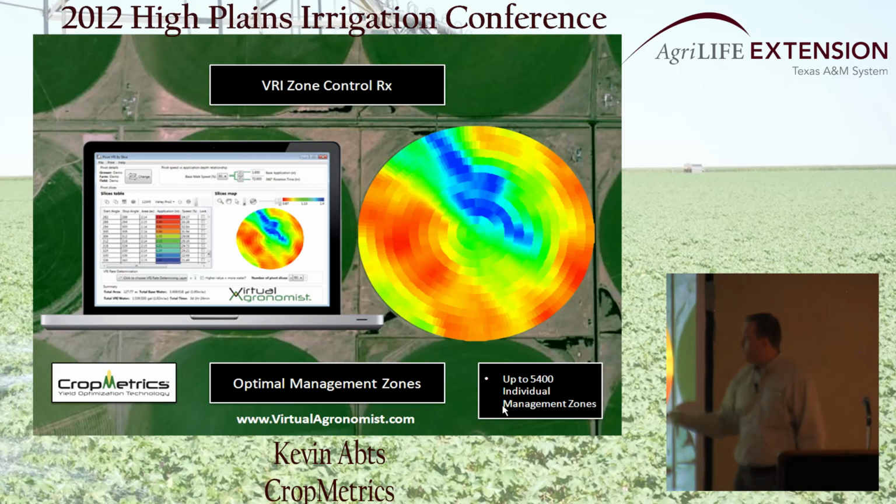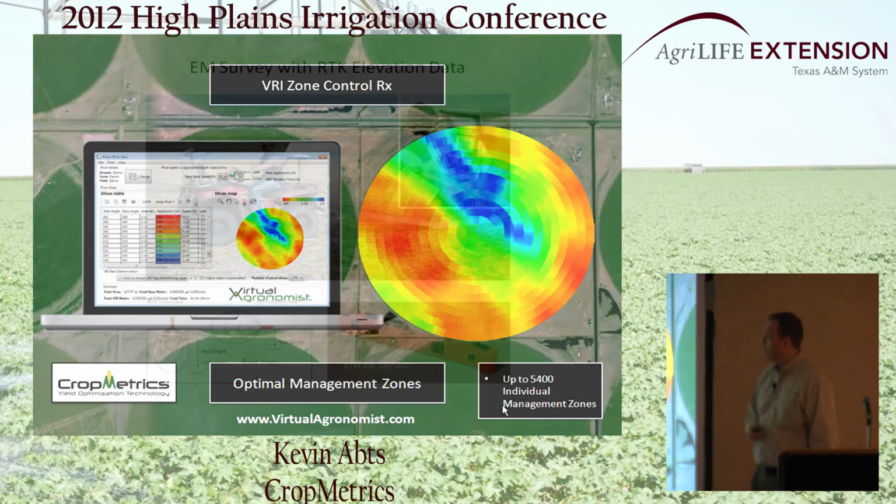And so we have the ability, for this particular example, to change the application depth across 5,000 different individual zones within a single 130-acre pivot, and we can do that as frequently as needed based on the data and the software. To us, this is the enabler that allows us to agronomically apply the water using VRI versus simply applying the VRI for non-cropping areas. So that's the zone control and a sample zone control prescription.